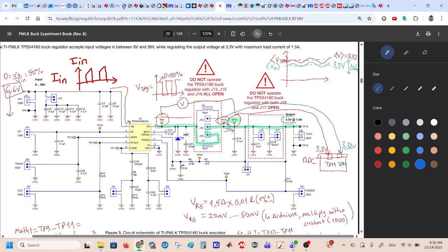But for the analog digital channel, the maximum voltage for Arduino, I shouldn't give a voltage level which is bigger than 3.3 volts. If I feed this voltage into the Arduino, maybe it will cut, or I don't know what kind of op-amp is inside the Arduino.